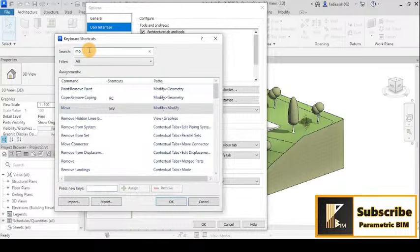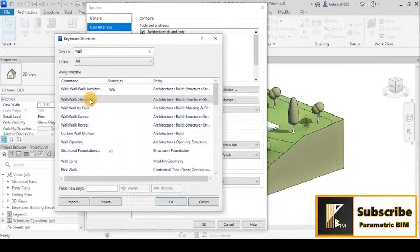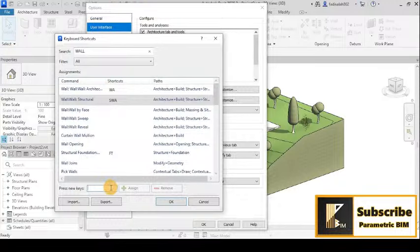But if you want to add, for example, something to a structural wall, maybe let's say SWA, and if I click OK, you can see that the structural wall has a shortcut SWA. But I will return it maybe to none or something like that. You can do anything you want.